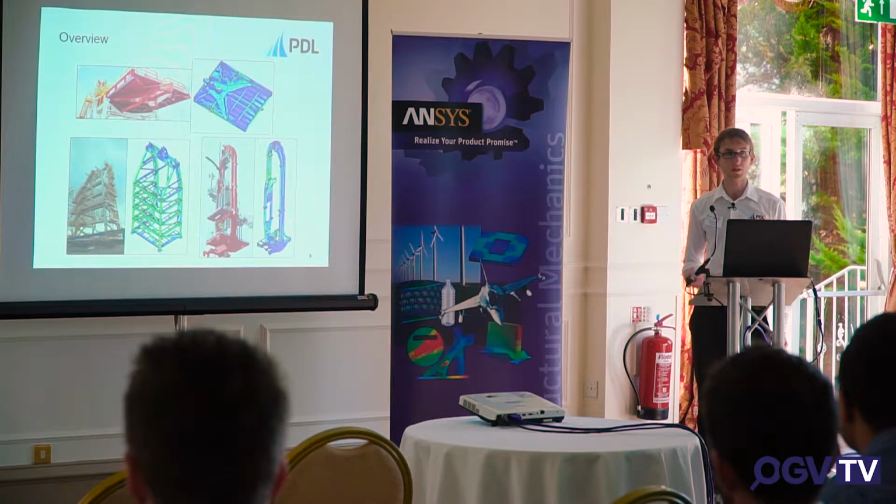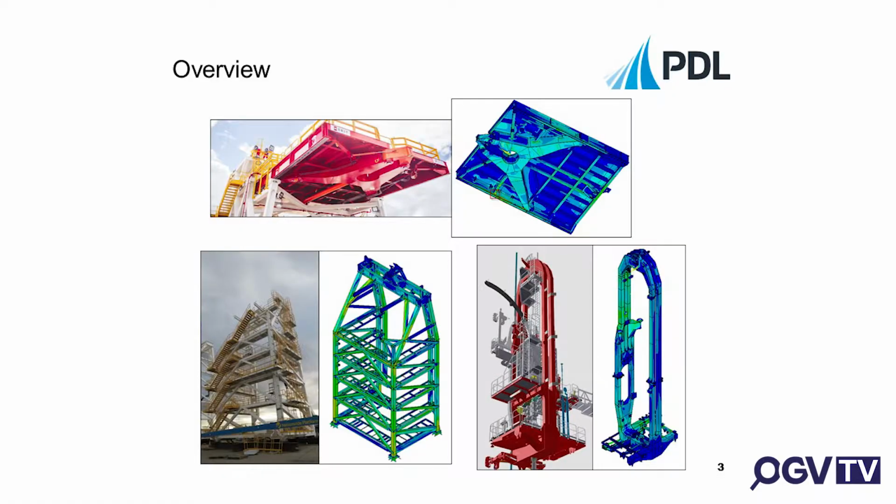If anybody is not familiar with the concept of fatigue damage, all it is is the number of loading cycles you expect to get divided by the number of cycles to failure. Cycles to failure is calculated using an SN curve and a stress range. So this is what we use to post-process.